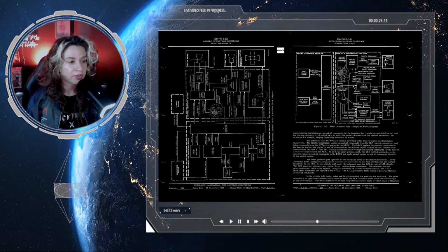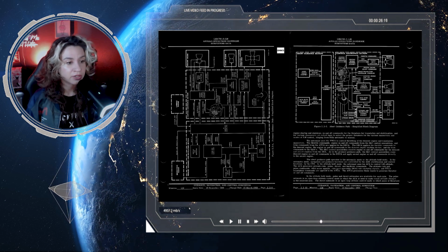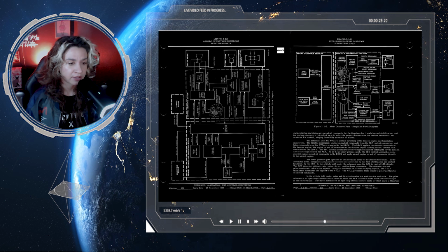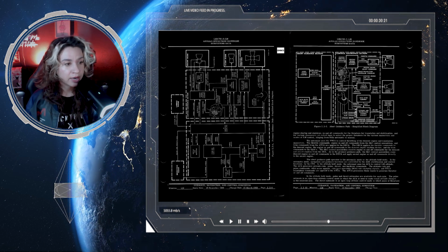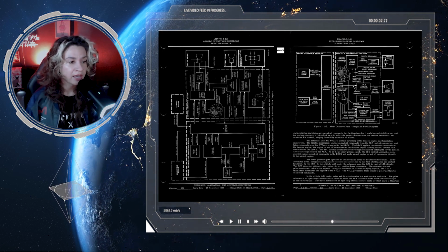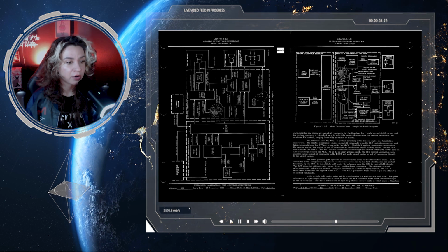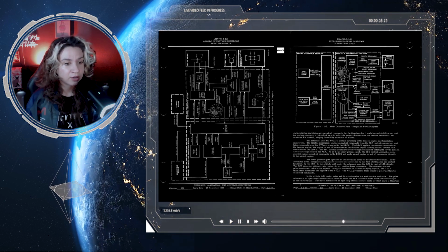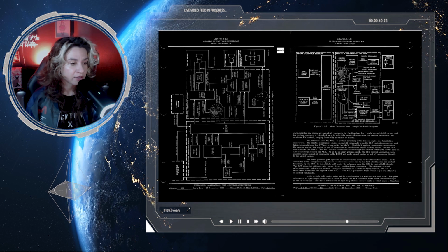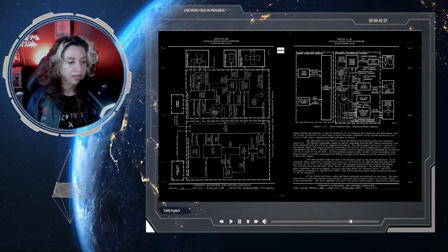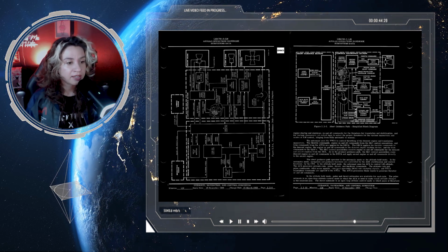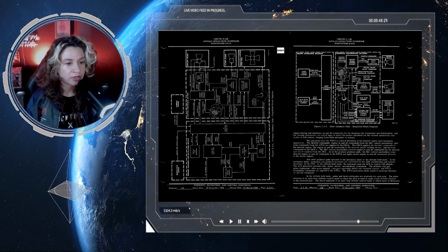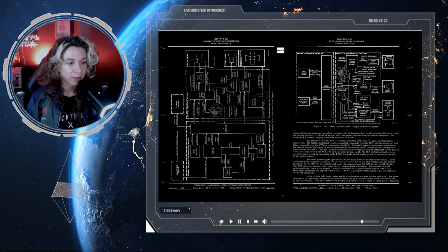The ACA generates an attitude rate pulse, direct, and hard-over commands. The attitude rate and pulse commands, the AEA error signals, the rate gyro assembly or the RGA, the rate damping signals, and the TTCA translation commands are applied to the ATCA. The ATCA processes these inputs to generate thrusters on and off commands.